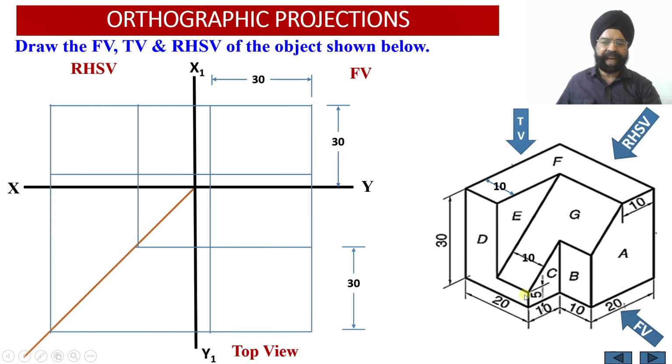So we have evaluated that there is this edge, that is the left corner over here. We have to move 5 millimeter above the base so that this slant edge bottom point will be located over here, right? This is the slant edge of this particular solid corresponding to the surface G. It is starting from the top, after you move from the rightmost corner 10 millimeter towards the left corner of the solid. This is the rightmost corner of the solid. As we move along 10 millimeter towards this side, one point, that is this point, will be located.